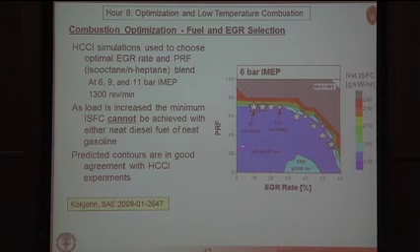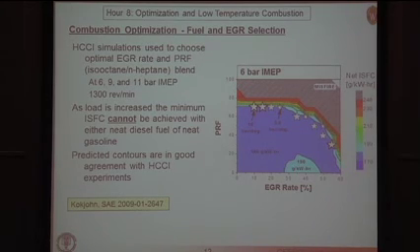On the other hand, if you had a fuel that was more like gasoline, say with a PRF number of 70–75, you have the possibility of operating with very low EGR rates. Now, EGR is expensive in an engine. You have to send that air back, complex air management technology. And it also costs you in boost pressure. So you really want to try to operate with as low EGR as possible. And so there seems to be an advantage to going to a fuel that's somewhere between diesel and gasoline from the standpoint of this operation.